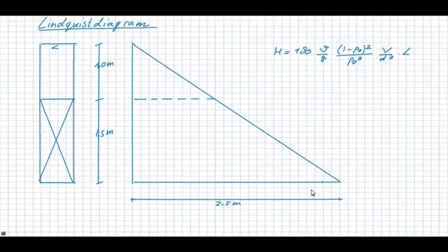Here we assume a total pressure drop of 20 centimeters over the filter, and we can draw the clean bed pressure line in the diagram. As said, during clogging the resistance increases and the pressure drops further, mainly in the top part of the filter. The pressure line at t equals 1 can then be represented as follows.